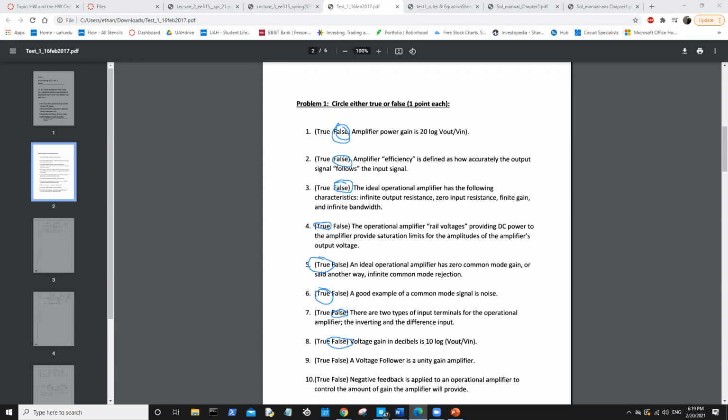All right. So what did you say again about the unity gain amplifier gain? Is it negative? A unity gain amplifier is defined as an amplifier with a gain of +1, just 1. Okay, just 1. So it just passes signals, which is why I defined it as a type of buffer. A voltage follower is summarily defined as a unity gain non-inverting buffer. Voltage followers are in fact unity gain amplifiers. If you ever see the word follower, assume it's a buffer, and if it's a buffer, assume it is a unity gain amplifier.